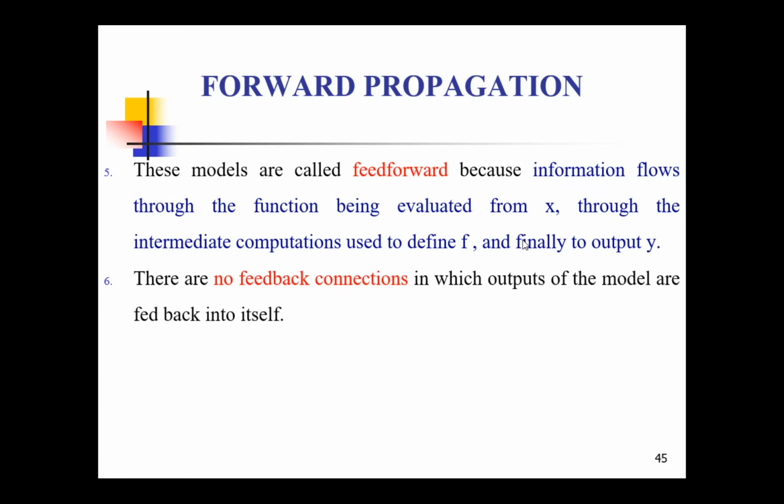Once it switches off, the temperature may rise. But in a closed loop system, I measure the existing room temperature. If the room temperature changes, the compressor has to start again, so that the desired output of 22 degrees is maintained.